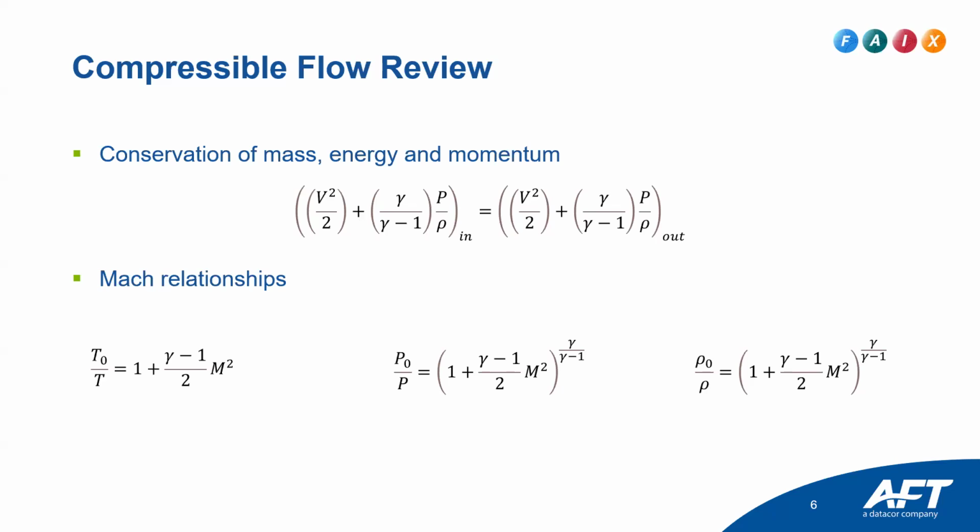Could I use the separator tool to model an existing compressor system in the field and to estimate water dropout from intercoolers or aftercoolers in my compressor system? As far as water dropout from them condensing, no. Well, you could if you put it upstream of the heat exchanger, but you would have to know the mass flow rate that the water is leaving the system. So you would already have to assume that, but maybe you could calibrate it with other field data. You might be able to do it indirectly, but it would depend on what data you have.